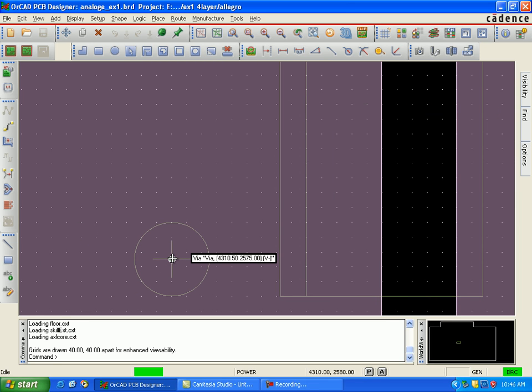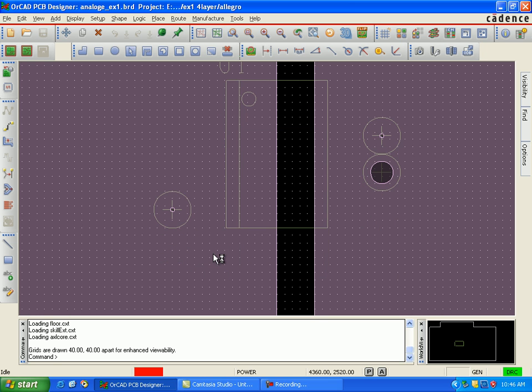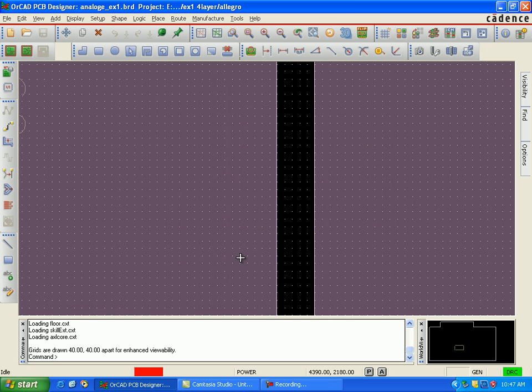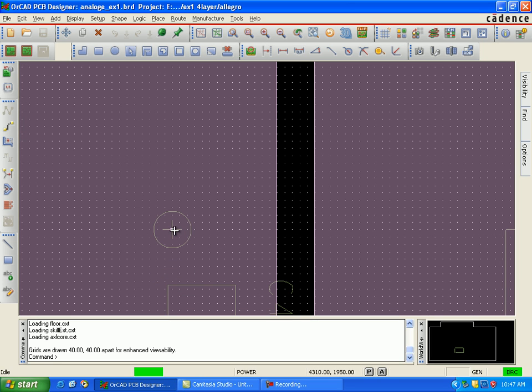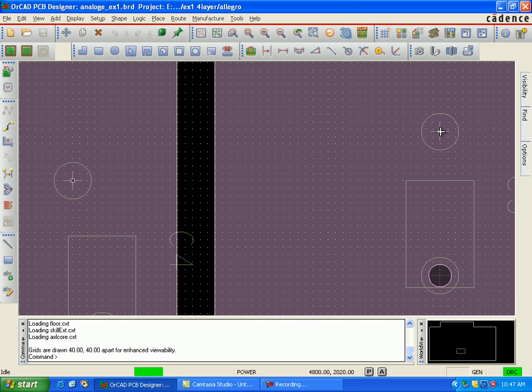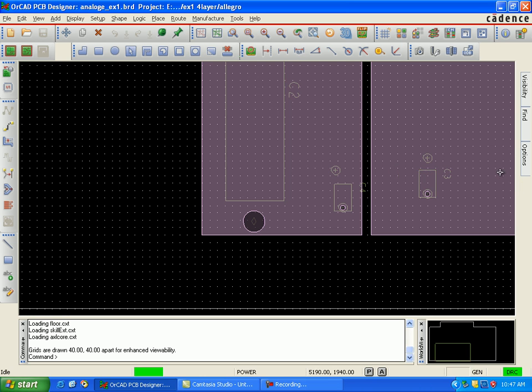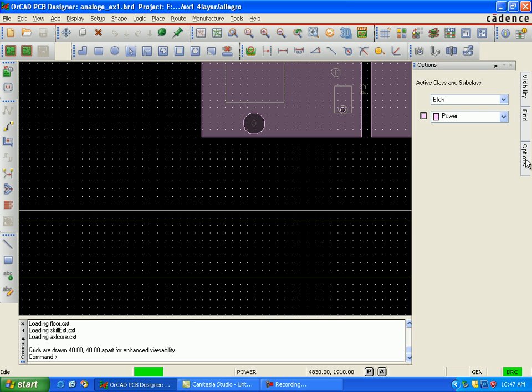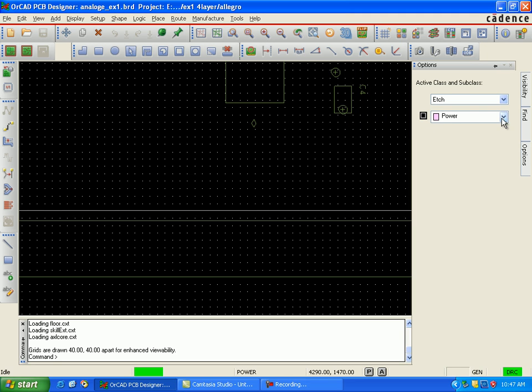This is the via. 2 vias we have connected in the V plus layer. This one is V minus. This is the via for the V minus. In between is the U1 op-amp. This is the via for V negative. So this will act like a bypass. If you place a component, it will bypass and directly connect to the ground. So these are the SMDs, or through-hole components. They will touch the ground directly.